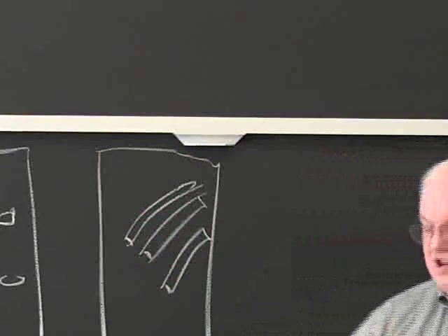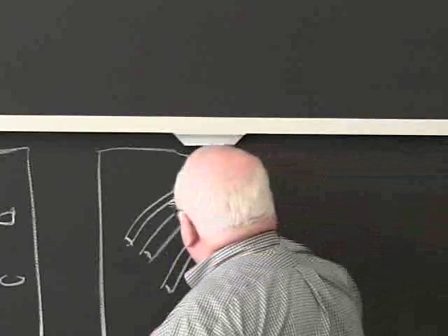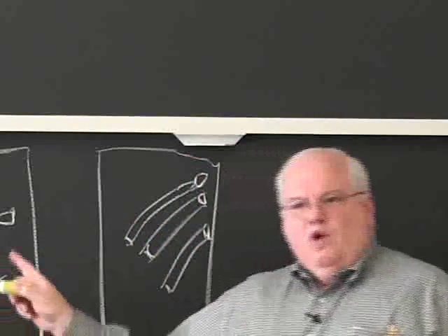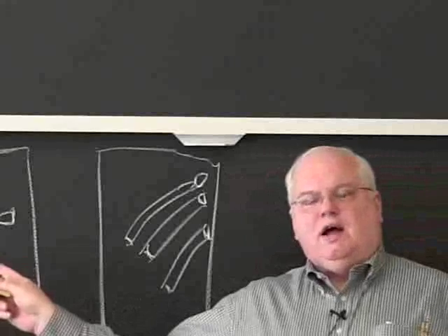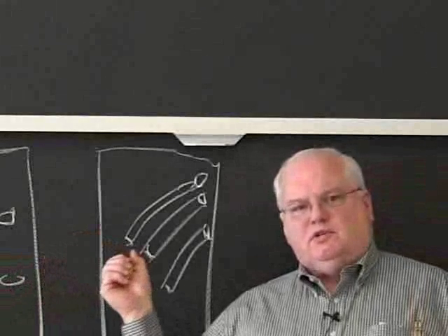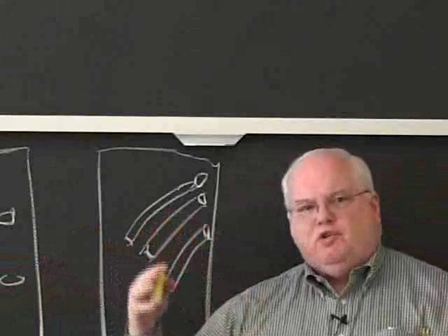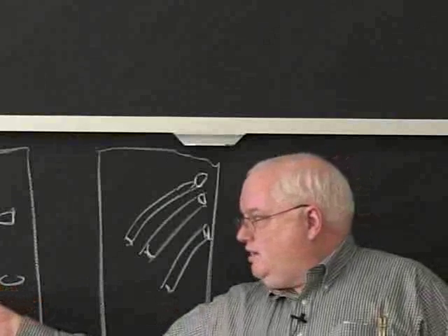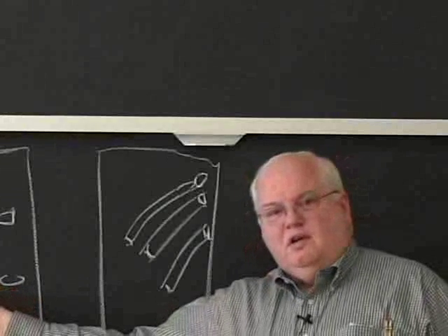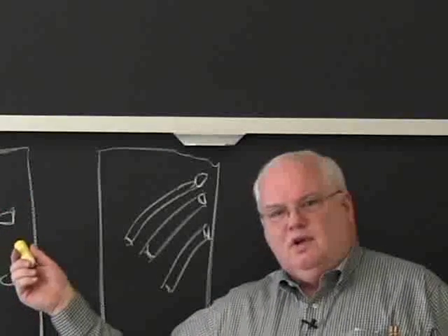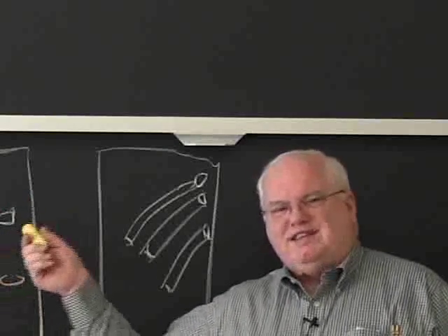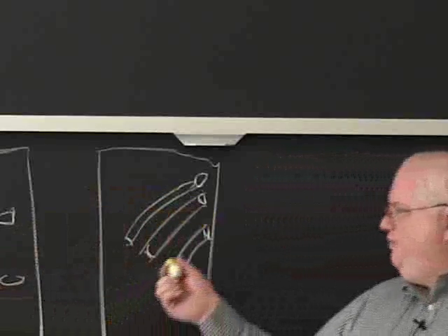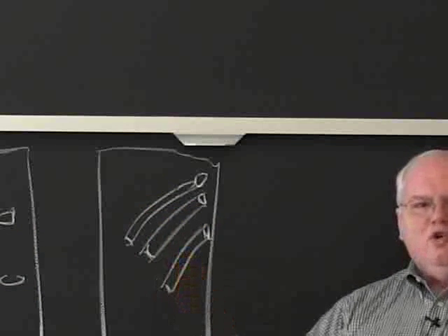And this is, or actually cylinders, okay? Plates or cylinders. But just think of these as little cylinders. And the question is, will the alloy want to form spheres, or will it form cylinders if you heat treat it, recrystallize it, and let the grains grow? It turns out that the minimum surface energy for a mixture of spheres, if you have less than 30 volume percent of your second phase, is spheres. Above 30%, you're going to want to form fibers.